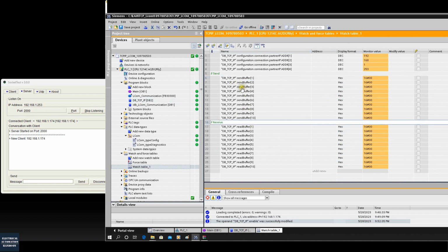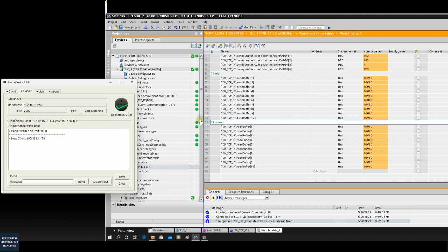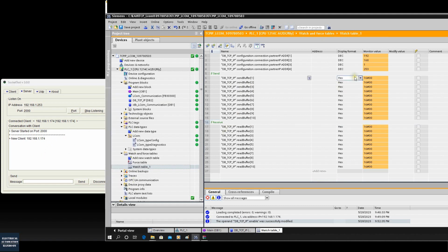While we are sending the data to the PC, it is actually running as char, as I introduced before, so you can see the ASCII table. We need to select the char right here. If we are going to send ABC, click transfer, click modify. While we are sending ABC, if we switch to hex, it's sending 41. This is the ASCII. If you check the ASCII table, you will see the A represents 41 hex.